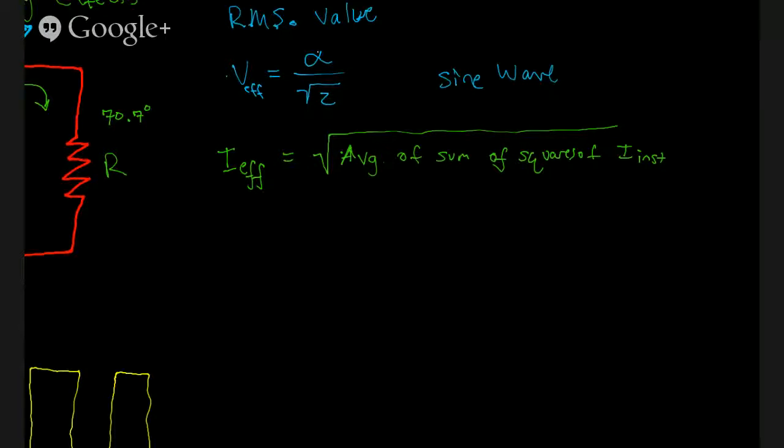And so if we have our RMS equation for a sine wave here, we'd find out that, plotted against our very rough sine wave, if we drew a line at about 70%, that'd be our RMS value. And we get that from just up here, 1 over square root 2.